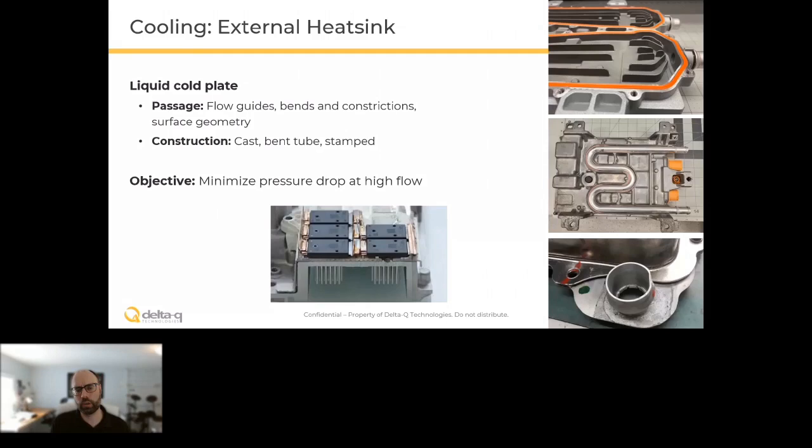What you're seeing there in the middle bottom is something quite different. So this is, I believe, a Tesla Model 3 traction motor drive, where they have very high thermal density. So you've got silicon carbide FETs there that are closely coupled to the coolant passage, and they've actually added lots of these pin fins to increase surface area and maximize heat transfer. That's not usually the approach that's needed in an onboard charger, just given its power density.